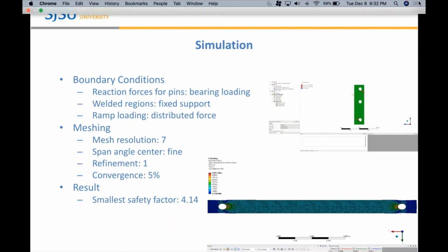Lastly, for the most critical of parts, we also used the convergence tool. This was enabled for the von Mises stress and set to 5%. This would result in the mesh being iteratively refined until the current simulation result had less than a 5% difference with that of the previous iteration, ensuring the best possible results.